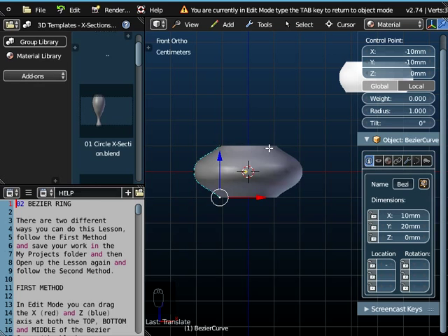So at the moment the settings for this ring are that distance there is 1 centimeter. We can see that from the grid. Also, if we look up at this table here, if I select that control point, X value, the red arrow is the X value. So this point here is at point -10. Minus just means to the left of the z-axis. I can't select the control point on the other side. This point here is +10, so that's 10 millimeters to the right. -10 is 10 millimeters to the left. So this is 2 centimeters or 20 millimeters diameter.